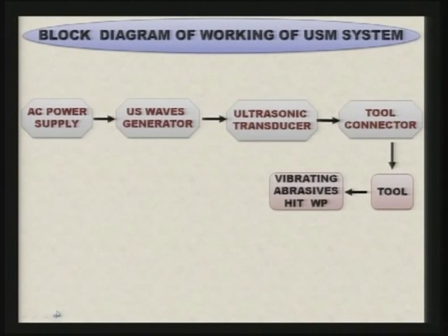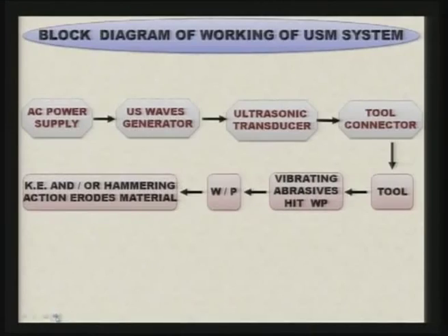So, this tool vibrates at ultrasonic frequency. As I will show you in the figure, there is a vibrating tool, there is the workpiece, and in between the two there is the slurry, and this slurry consists of liquid as well as abrasive particles. When this tool is vibrating at ultrasonic frequency, it is hitting thousands of abrasive particles present in the slurry under the tool, and these particles move towards the workpiece.